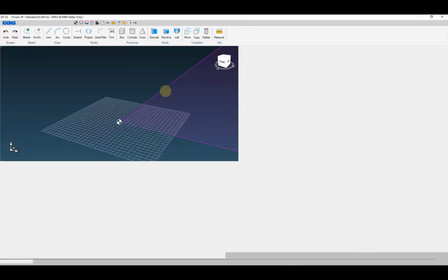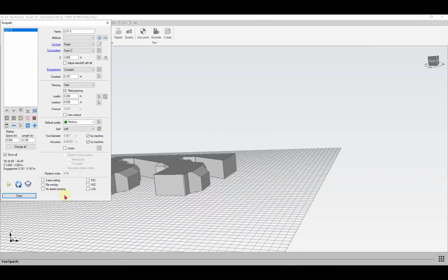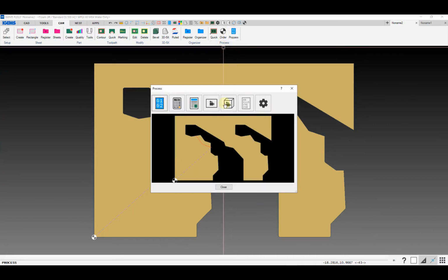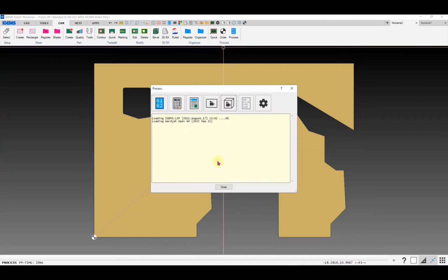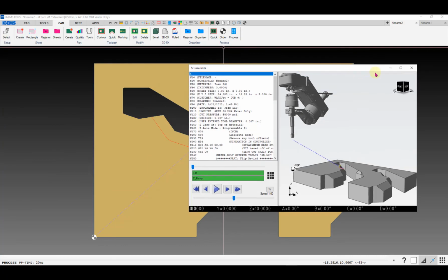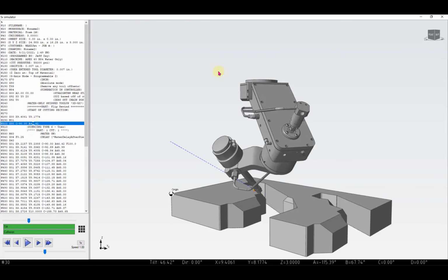So double click on the part again to edit it and go back to our tool path, and down here at the bottom you've got the flip windup checkbox. Create update part, and no rewind. And now we're starting at C of negative 90.